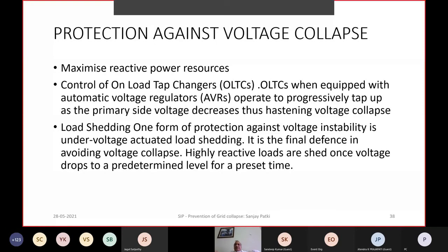So you all must be aware now, at 400 kV level, there are many STATCOMs which are now being commissioned as a result of this great disturbance, so that the voltages can be maintained on many of the bus bars. Still in India, there are many 400 kV bus bars where during peak load condition, voltage levels are still poor at some times.